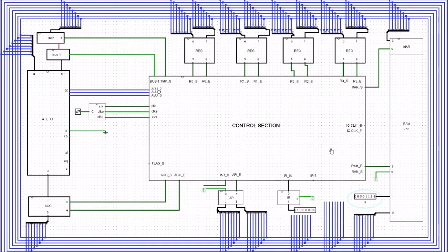So really, the next address that we're going to use as our instruction is going to be the contents of the first memory location inside the RAM. So let's count through our first 12 to get to the clock pulse that we need. Okay, so that's the 12th clock pulse come in. So let's get inside the control section and we'll see what this looks like.